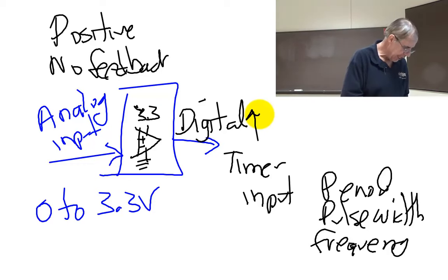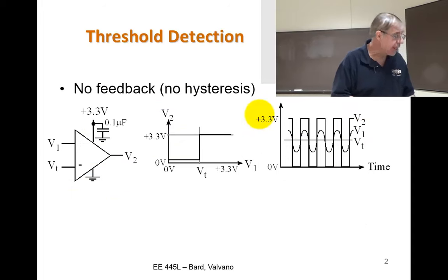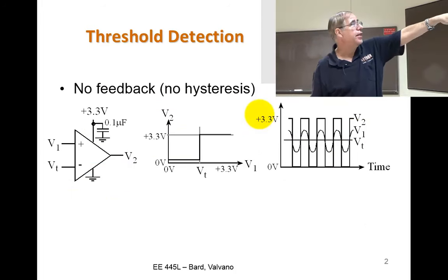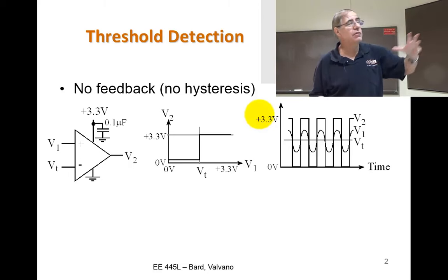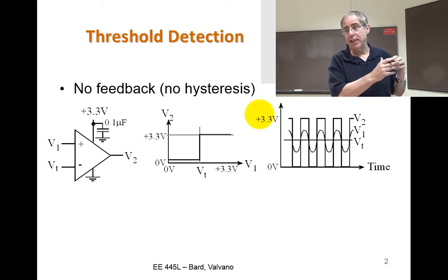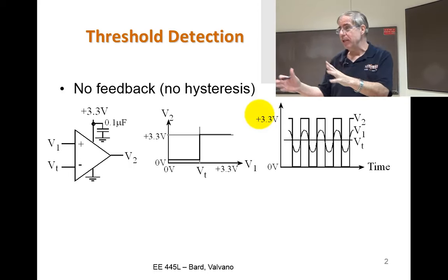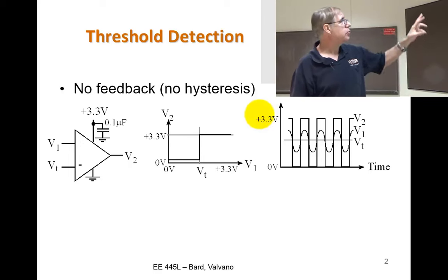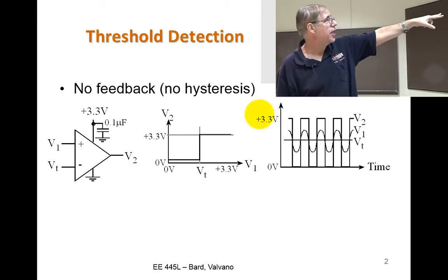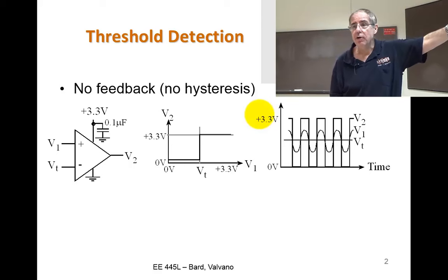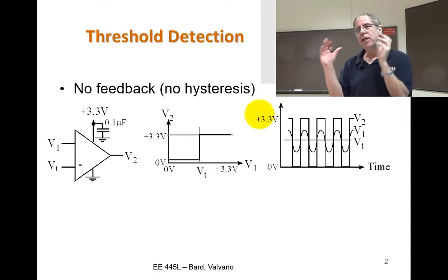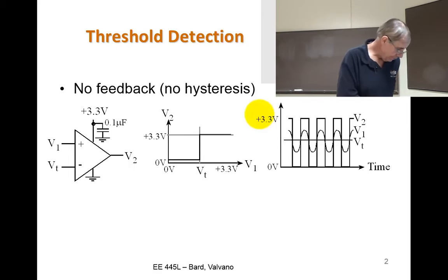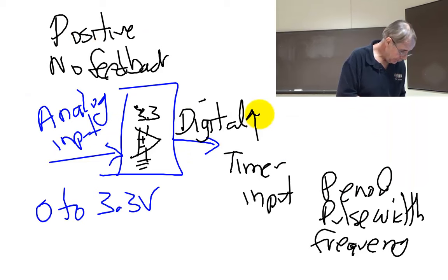This is a very important class of interfacing, okay, that allows us to take things that, like in this case on the right, the input is analog, and embedded in that is the period of something interesting, and we just roll it through this OpAmp with the appropriate threshold voltage, and out comes a beautiful square wave at that same period. Okay? Something really bad happens if I zoom in to that waveform. All right, something bad happens.